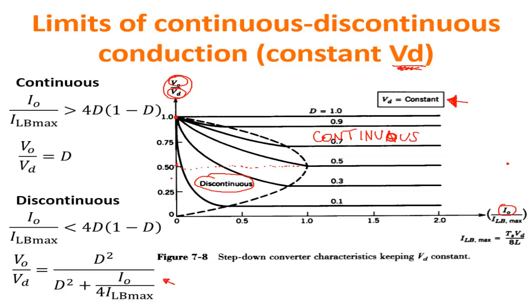But there are additional architectures in which you can use the same inductors for more than one DC-DC regulator. So you have a smaller number of inductors than the DC-DC regulators that you have inside the chip. These are more complex architectures that we are not going to see together, but just to give you a complete picture of the whole thing.